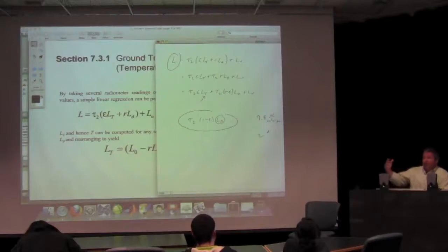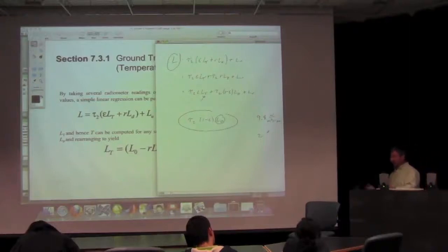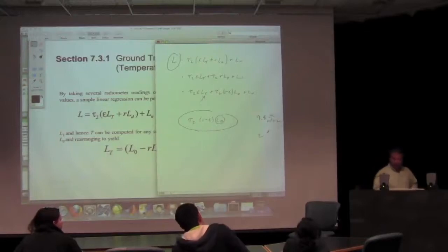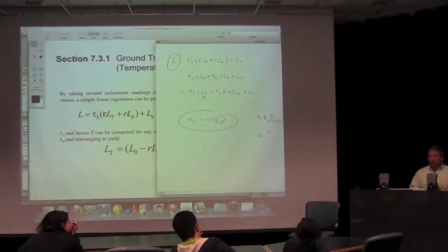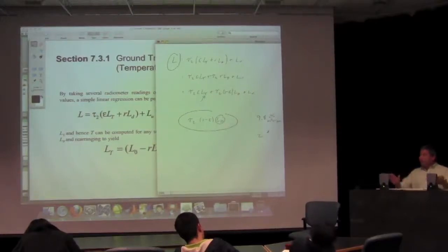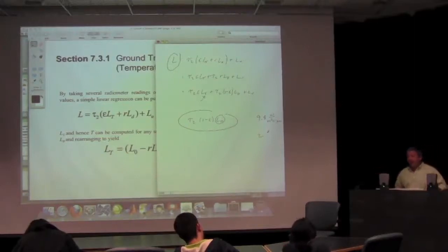Now, if you think about what a particular material is and what its optical properties are, and what its emissivity in particular is going to be, most things in the world are fairly high emissivity. Polished aluminum, not true. That's a fairly low emissivity. Aluminum foil, low emissivity. Gold, low emissivity. But these aren't things that you usually find lying around everywhere.